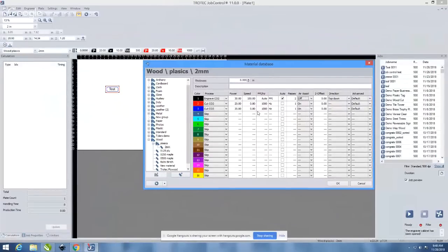Yeah, and if you're cutting anything, most likely you need the nozzle on. Most likely, yes. The only exception would be something like paper, where the air might blow the pieces around. But for most heavier materials, yeah, you would want to have it on. Perfect, thanks. And if you are doing papers and you're worried about it, you can always get the vacuum table to keep those papers secure.